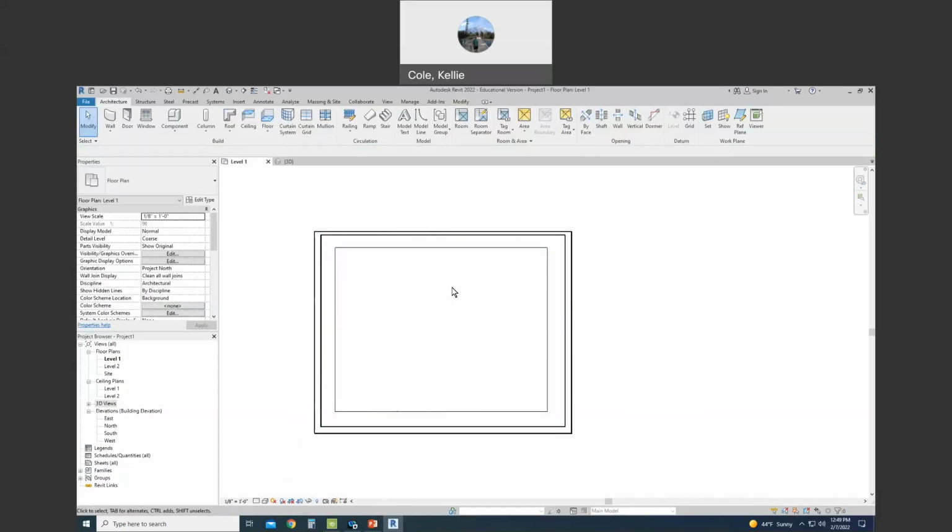I want to use an align tool. I want to align my walls I drew to these lines. Align helps in so many ways when we're drafting. Do we want to align a height or a width? Is it working? Yes, okay. So let's type in AL for align.